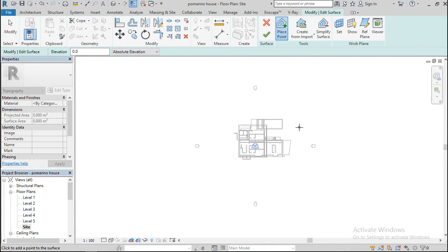But if you're going to import a contour from Google to AutoCAD, then to REVIT, you're going to get a much more advanced topo, a much more realistic ground surface with all the undulations and the rocky environment.